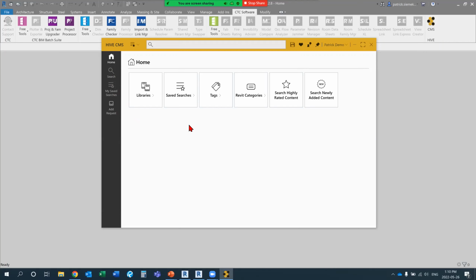As a Revit user comes in, instead of always looking for files somewhere on the server or somewhere locally on your machine, one of the nice things about HIVE is saved searches. If I were to start a brand new project, at the very top left, I could click inside this area and see some saved searches. Right here, there's one saved search called Revit templates. To the right of it, there's a little icon showing that this specific saved search is provided throughout the whole organization.